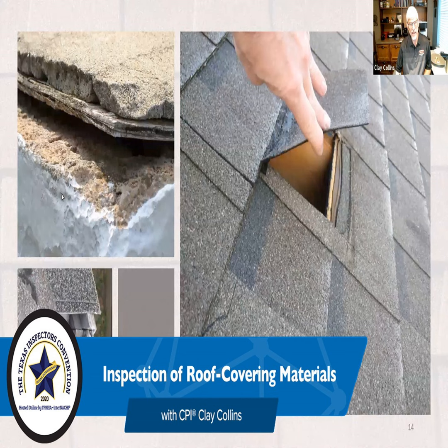But that 1/8 inch spacing at ends and sides is what allows for the expansion of the decking without impacting the roof cover itself. Now, H-clips are what we generally see to create that spacing.